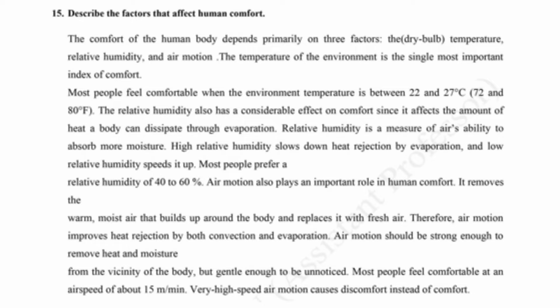Air motion should be strong enough to remove heat and moisture from the vicinity of the body, but gentle enough to be unnoticed. Most people feel comfortable at an airspeed of about 15 meters per minute. Very high speed air motion causes discomfort instead of comfort.